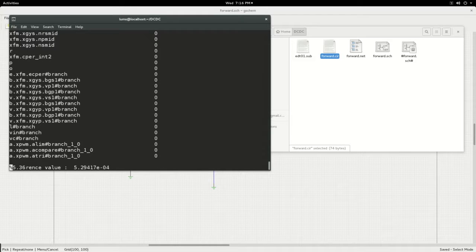So this will take some time. I will later on tell you methods in which you can reduce the simulation time. The first time simulation will take quite some time, basically because you would have given an extended range till it reaches steady state. After it reaches steady state, you can then note down the steady state value and give it as initial conditions, and do the simulation with those initial conditions.